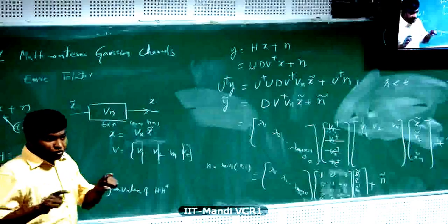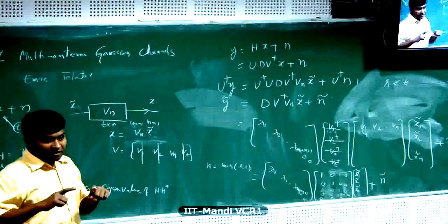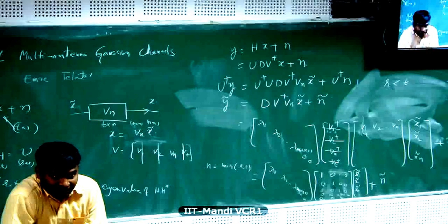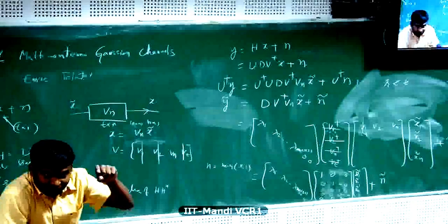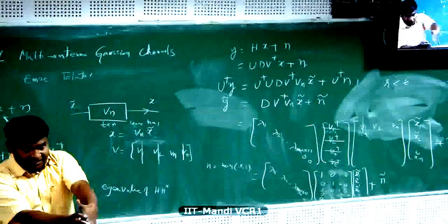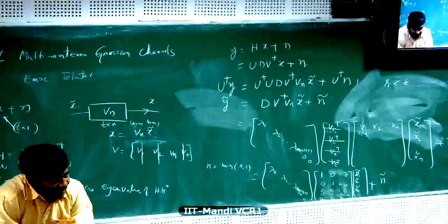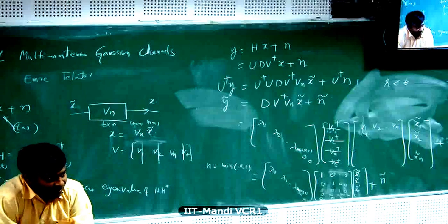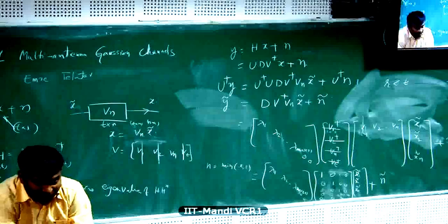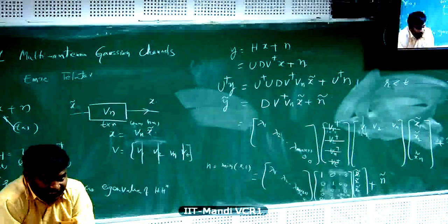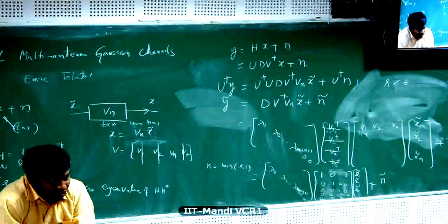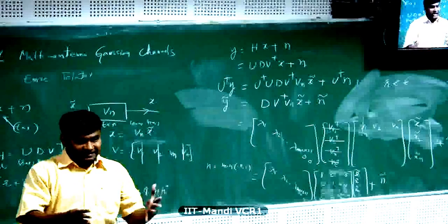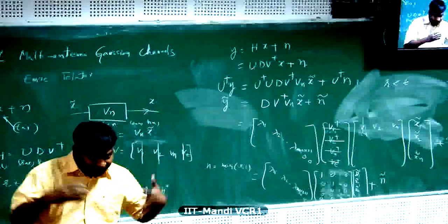Okay. I gave you a single stream example, right? How many antennas did we use? All antennas. What did we do? We put weights such that all the energy is coherently combined. Right? That was easy to see. Do you want me to go through that example again? No. Okay? You have two antennas at the transmitter. Instead of sending two streams, we sent one stream. So all the antennas are used to give what is called array gain. It's not spatial multiplexing gain, but it is array gain.